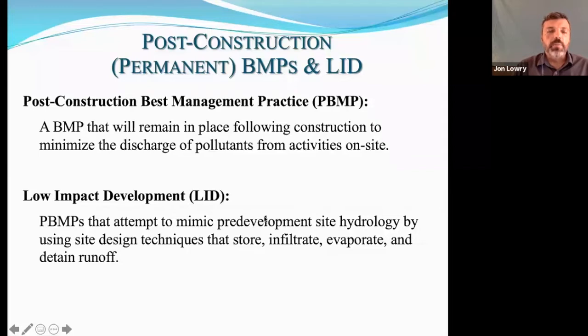And one of the BMPs that we try to implement most often is called low impact development. Low impact development is a permanent BMP that attempts to mimic pre-development site hydrology by using site design techniques that store, infiltrate, evaporate, and detain runoff.